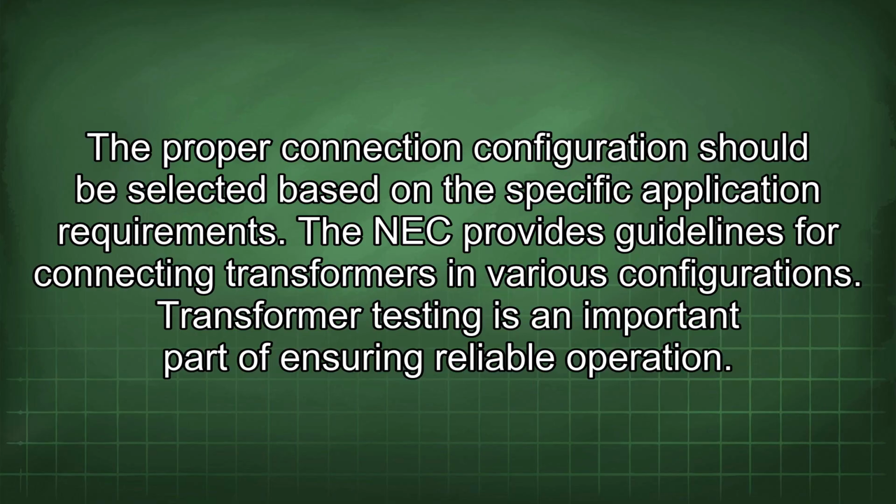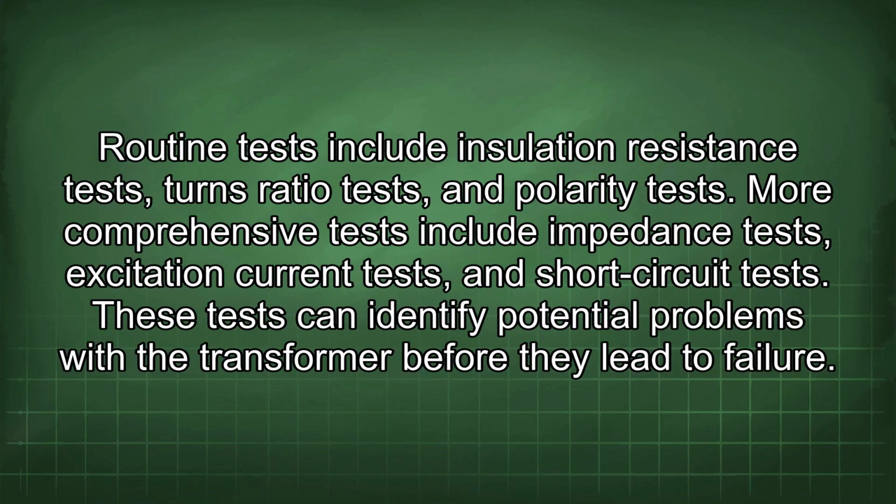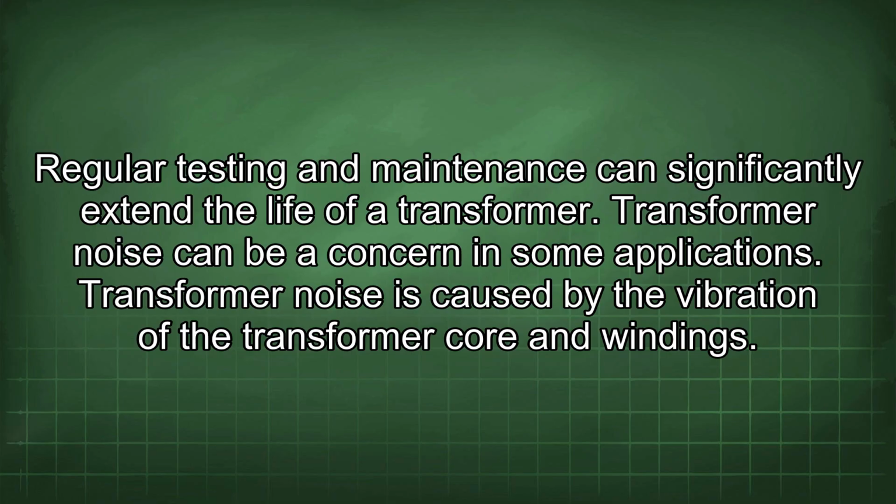Transformer testing is an important part of ensuring reliable operation. Routine tests include insulation resistance tests, turns ratio tests, and polarity tests. More comprehensive tests include impedance tests, excitation current tests, and short-circuit tests. These tests can identify potential problems with the transformer before they lead to failure. Regular testing and maintenance can significantly extend the life of a transformer.